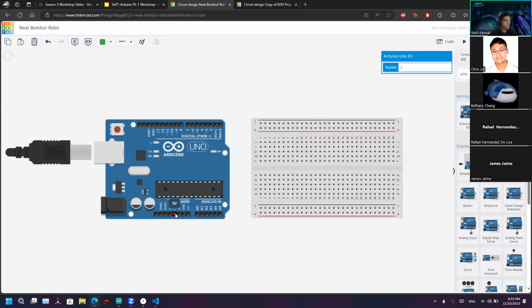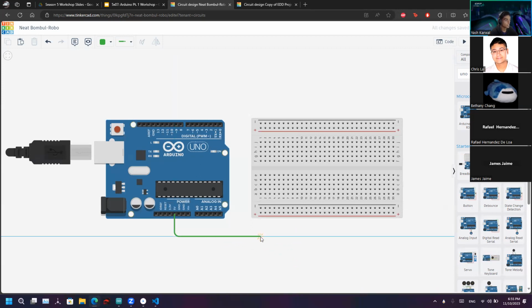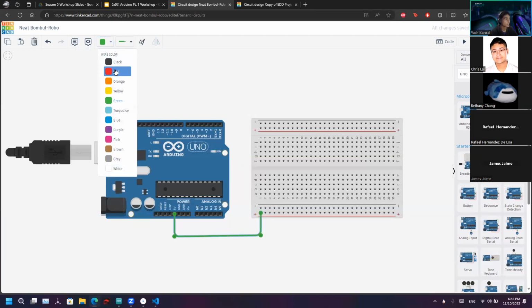So let's first talk about our bus lines. Let's power our bus line with 5 volts. So we have a 5-volt wire. You can left click onto it and drag it wherever. You have to hold it, by the way. You can move it and click once to create an elbow, which usually aligns it, and then click again. And then bam. You can also alter the shape later on. If you click on it, you can also change the color up here, say red for power.